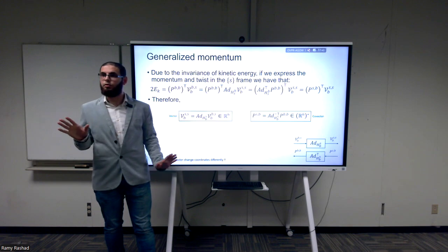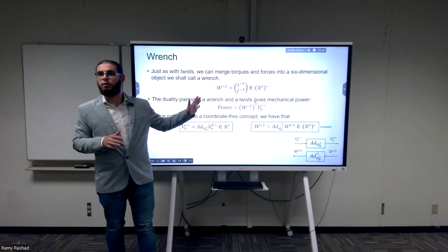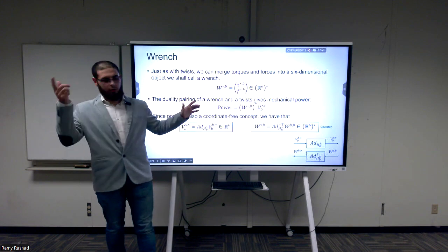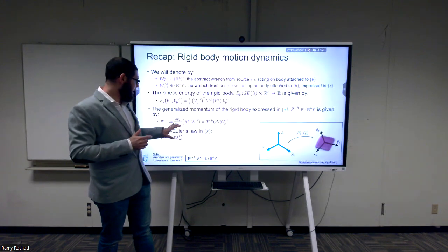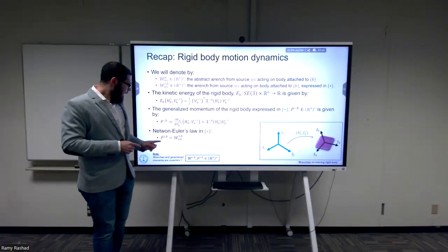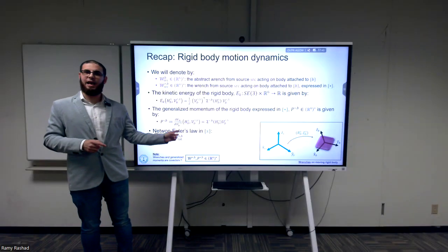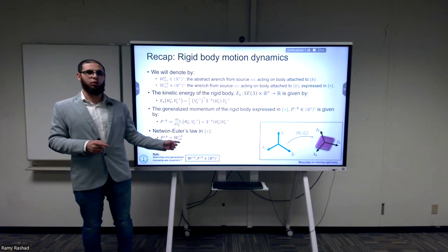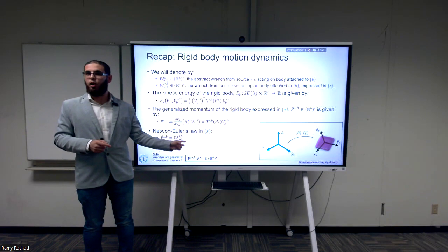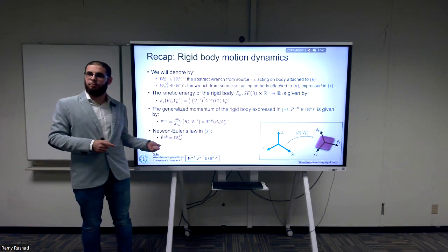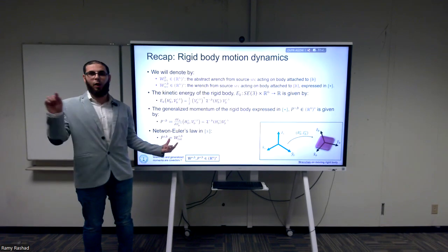That's correct. This is actually how wrenches are introduced. And another insight that you can get out of this: I can never equate two things except if they are in the same space, right? I cannot say that I have something that's a vector and equal to something that's a covector. And this is another proof that wrenches are equal to the rate of change of momentum, because momentum is also a covector. So this is another proof that the equality here is correct.